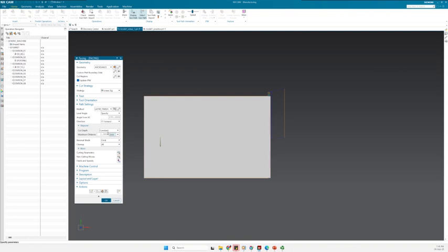This is something that you might also need when you are doing your assignment, since I might have defined the limitation of a depth of cut. In real life, this is something that you decide based on the specification of your drawings, the material you are machining, and the tool that you are using, and specifically the catalogs, what the catalog is actually providing you when you are doing the calculation.